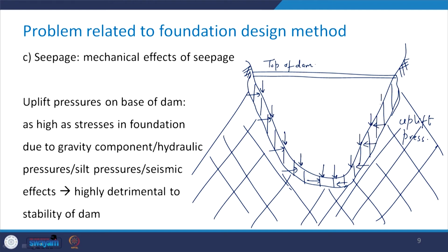Like this. This is your dam body. So, there is going to be the occurrence of uplift pressures on the base of the dam, and these can be as high as stresses in the foundation due to gravity component or hydraulic pressures or silt pressures or seismic effects, and therefore, these are highly detrimental to the stability of the dam.